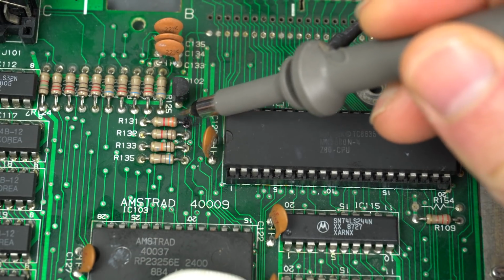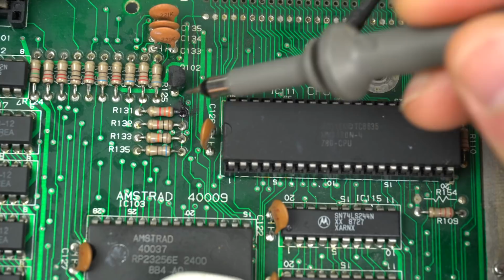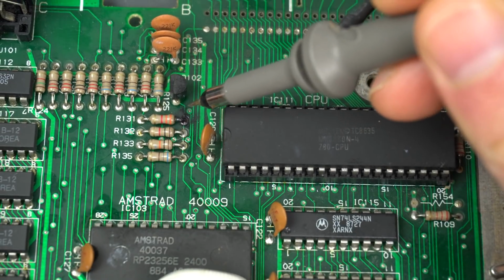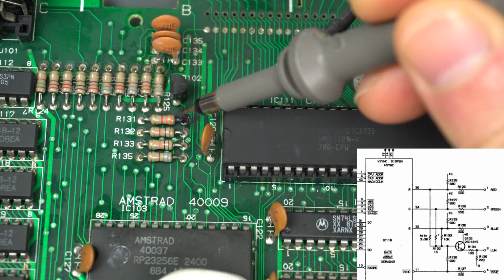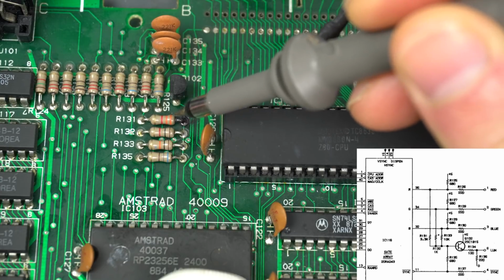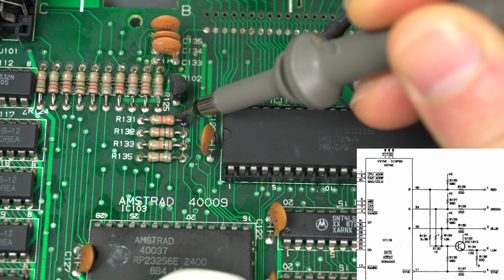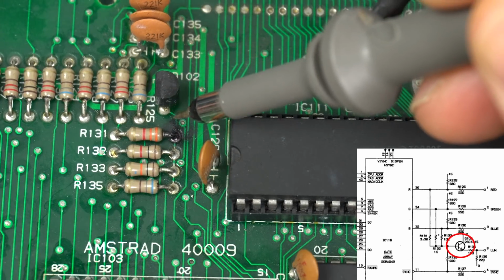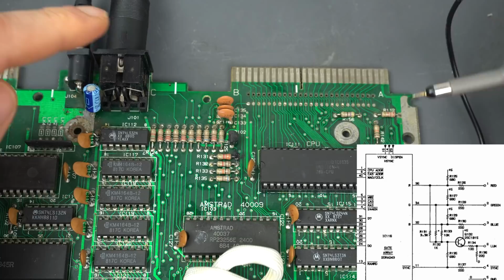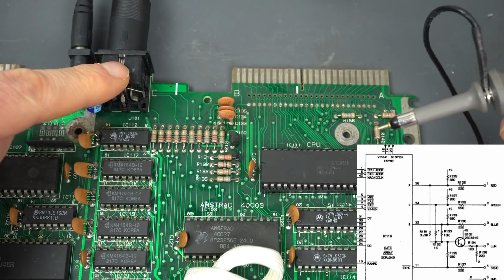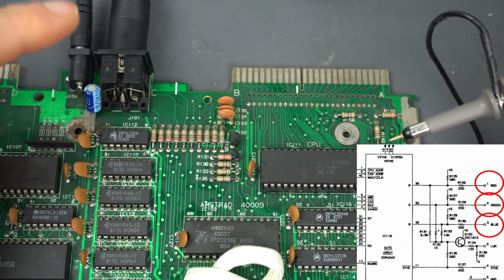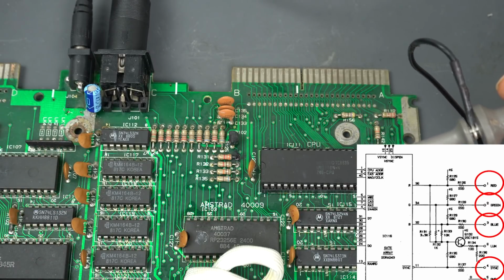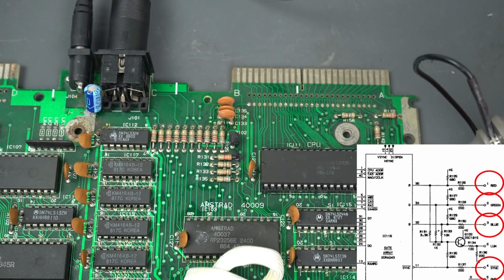That is totally scorched. So I looked it up in the schematics, and this is actually very interesting. This is related to the video out signal. It looks like this transistor is used to generate the luminance signal. So the signals out of the video connector are R, G, and B. There's a sync signal, which is what we've been seeing on the gate array.